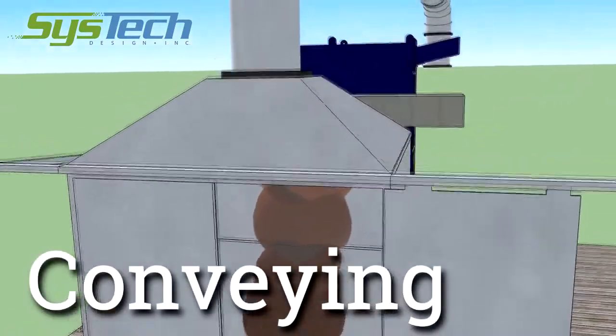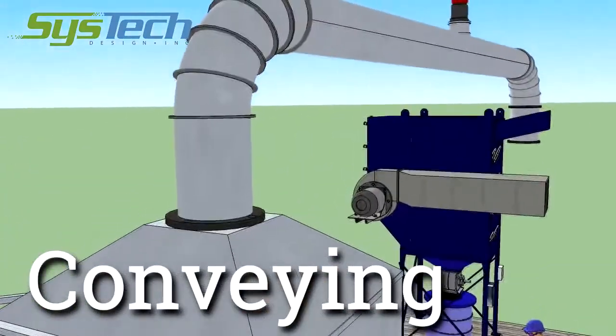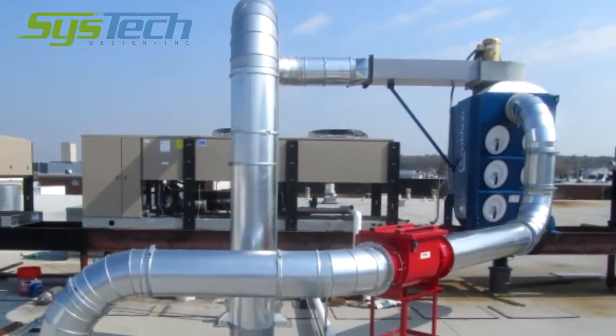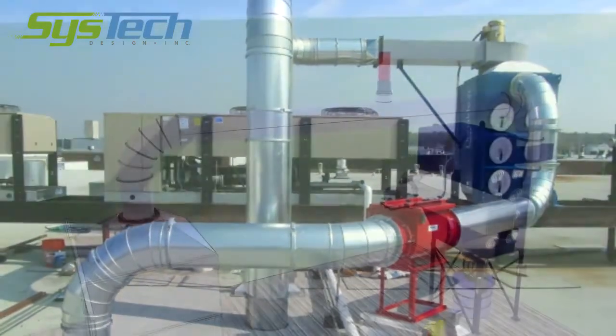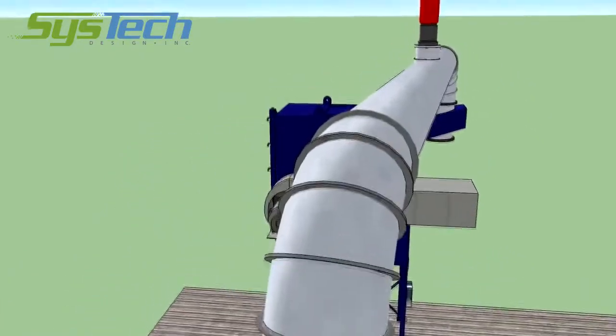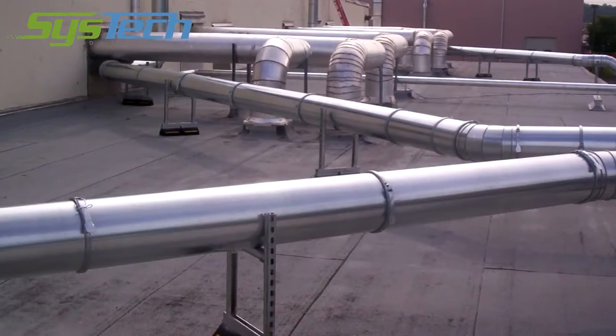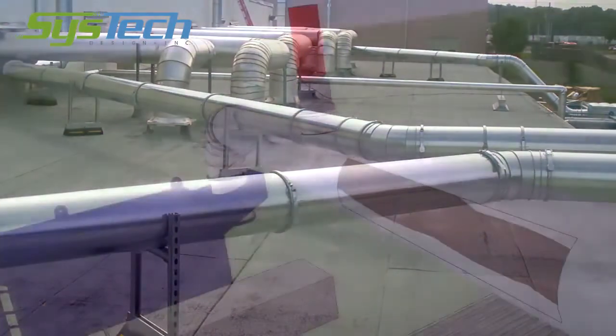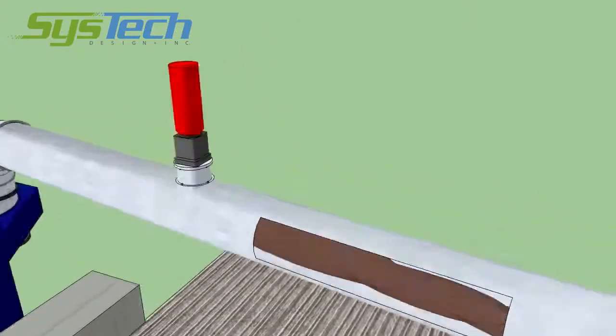Conveying is our second C. Duct diameter and airflow need to be designed with a carrying velocity to keep the captured pollutant in suspension. The lower the duct velocity, the less friction loss and required horsepower. At the same time, hood entry losses, branch entry losses, and elbow losses need to be considered. Again, the lower system pressure losses, the lower horsepower requirement, and both capital and operational costs.